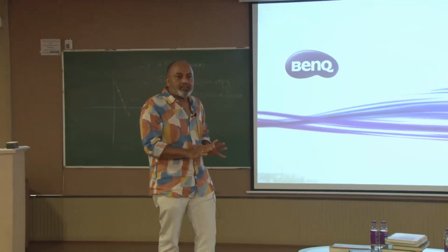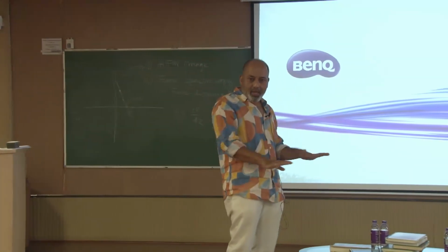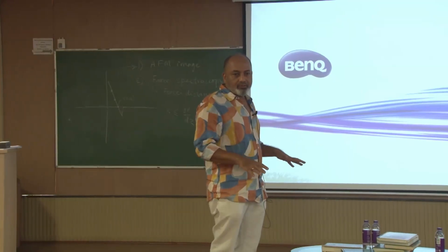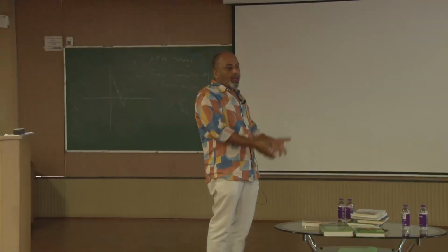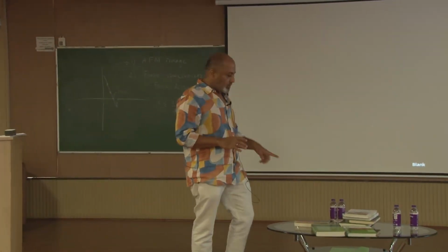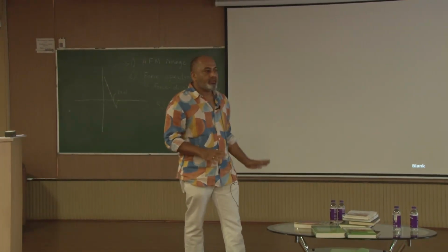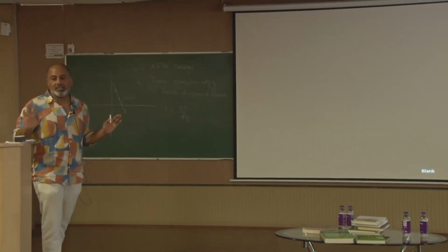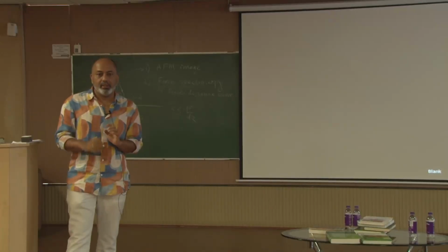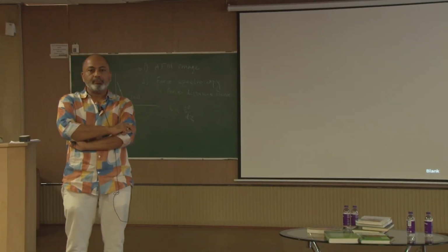At the moment, let us understand, if there is the same Young's modulus all over the surface, you will have to push and pull the sample up and down exactly by the amount of the topography over it, and it will produce an image. So, this is how imaging is done under AFM. Any doubts? Yeah. So, the force that we are saying,